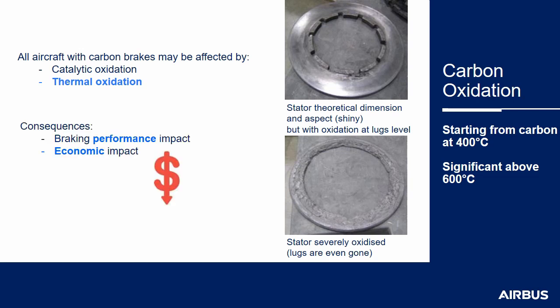What are the consequences of carbon oxidation? Oxidation affects the braking performance and can even cause loss of braking on ruptured brakes. Oxidation also has an economic impact. An oxidized carbon disc cannot be refurbished. The carbon cannot be reused, and thus it affects the brake life and the brake cost per landing.